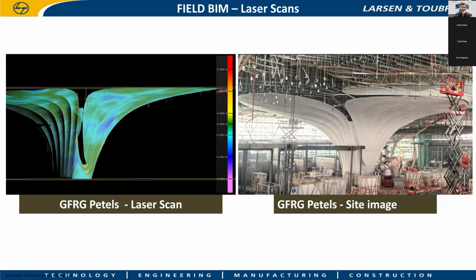After post concrete, it could be 3.95 in some location, 3.85 in another, or 4.01. You can capture that information through the SX12 by generating the heat map by giving the reference level. With that reference, it can read the surface area and identify the locations where it went down and where it went up.